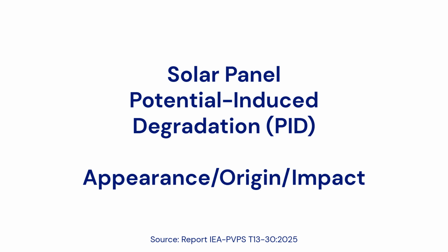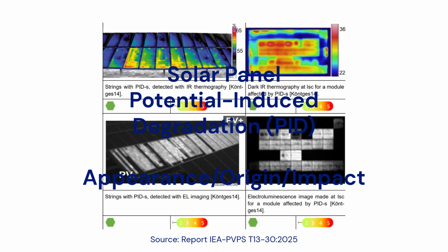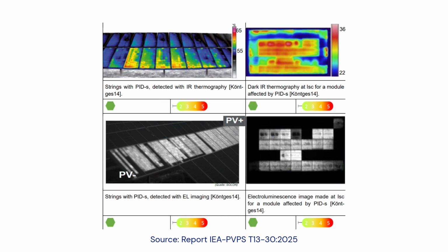Potential-induced degradation, appearance shunting and polarization type of degradation are not optically visible, however advanced stages of corrosion or delamination type degradation are visible. Potential-induced degradation causes a progressive power loss, and some degradation modes may also manifest in discoloration and hot spots over time.